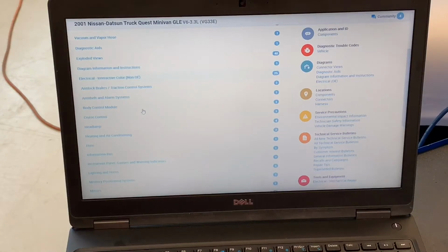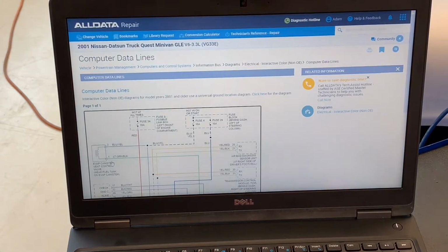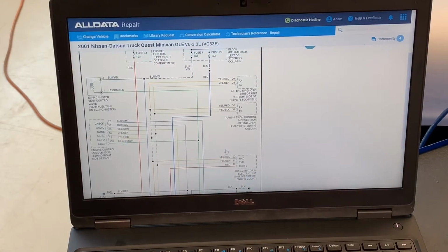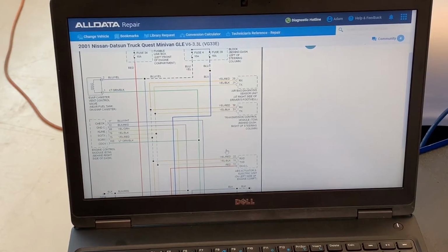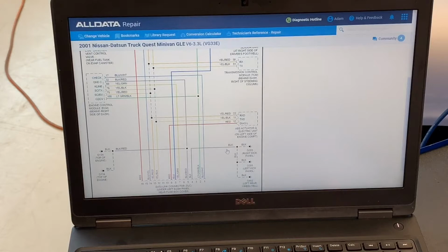So if we had a vehicle that had a serial communication fault, say a U code looking at a particular module for lack of communication, one of the things I really need in order to understand that sequence and make determinations about where to look is how that data bus network is wired. A lot of data bus networks are put in somewhat of a daisy chain, where the main line of communication goes from the data link connector straight to the ECM, and other modules down the line are connected on the other side in their own clusters. So a diagram like this can help me understand that.